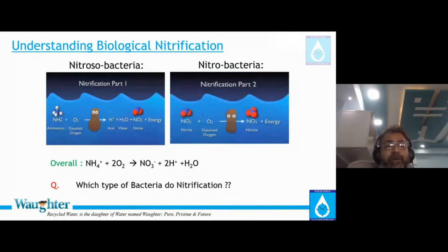There's one family called nitrosobacteria, which does nitrification part 1. They say, what I can do is take NH4+, which is in the reduced stage of -3, to a stage called NO2-. Beyond that, no, I'll become tired. Nitrite. So their friend will say, don't worry, nitrification part 2, we will do that.